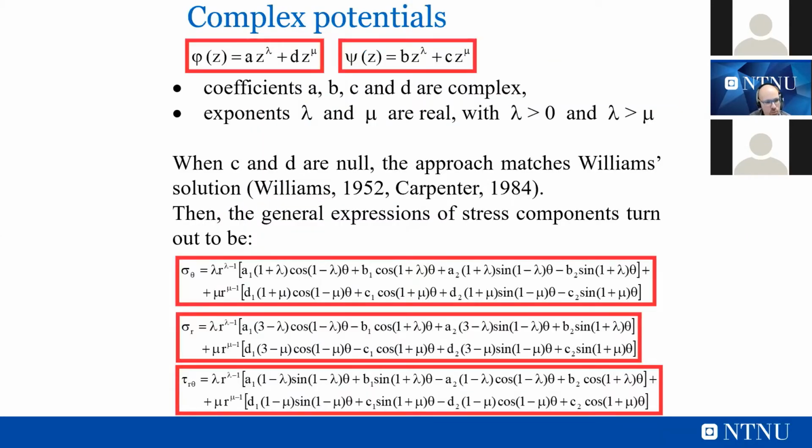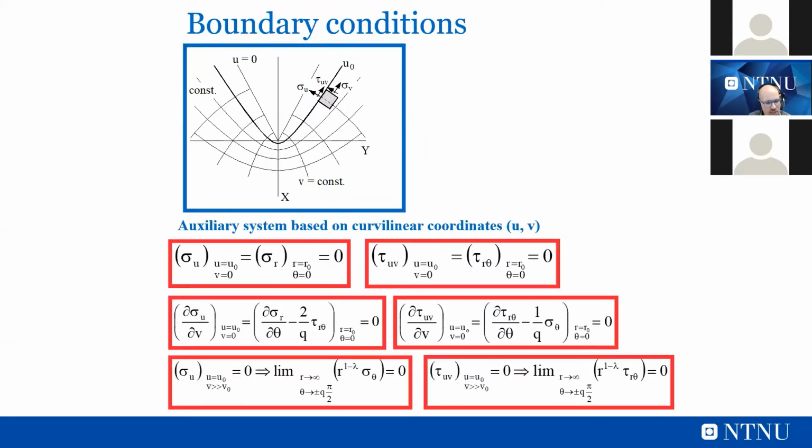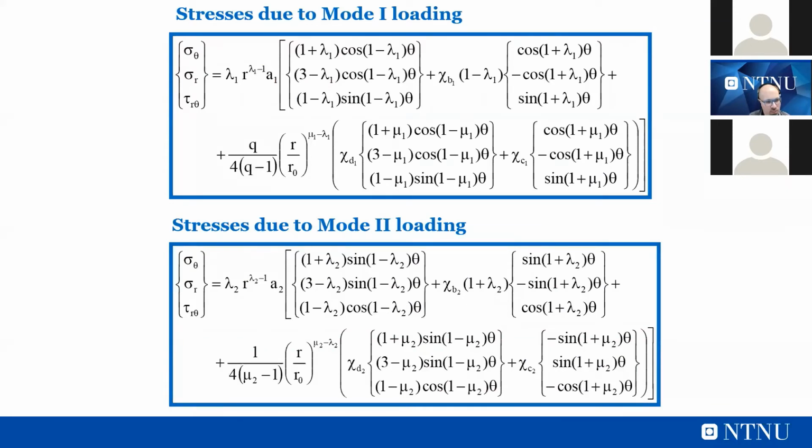And they were able to use the complex potential formulation, of which I don't want to give you the details, but it's only to show that the problem is really complex, both in terms of complexity and because you use complex potentials to solve it. Imposing very difficult boundary conditions, and according to a very difficult curvilinear coordinate system that they introduced for solving this issue, they were able to provide some nice mode 1 and mode 2 equations that give you the stress distribution in front of a notch, independently of the notch tip radius, the notch opening angle, and the notch depth.